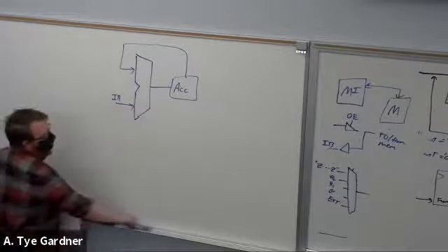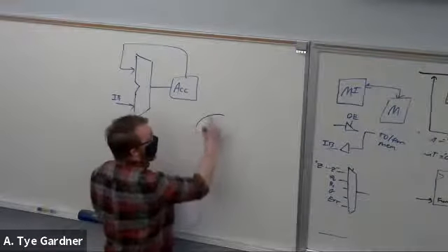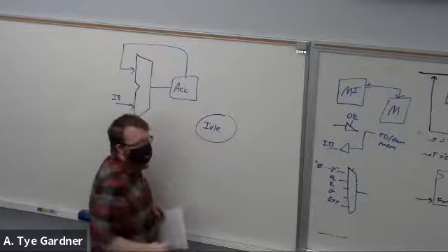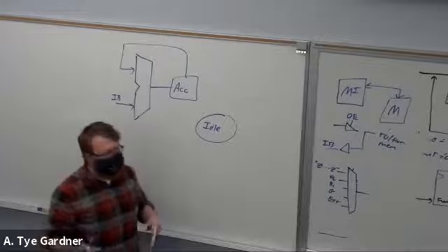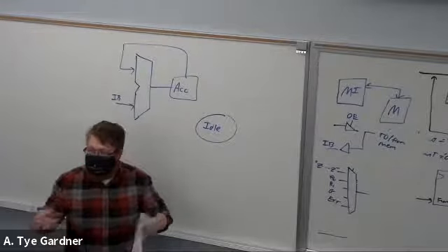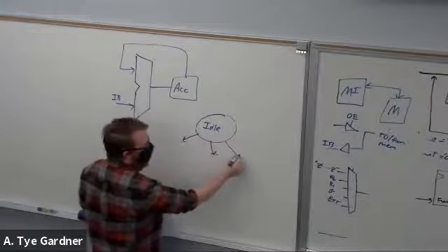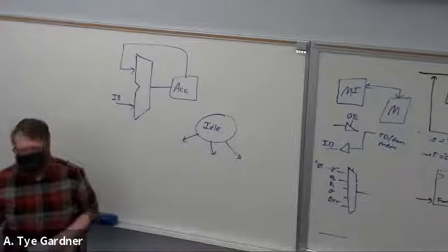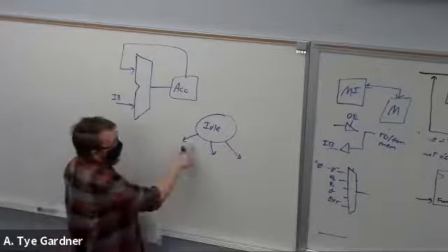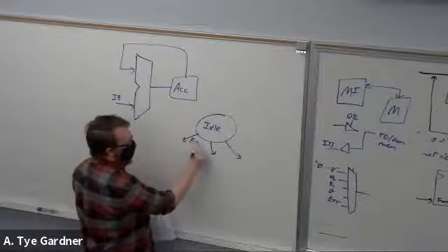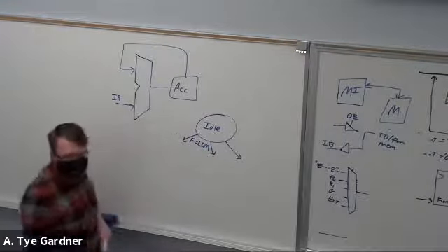So our state machine, when we start thinking about the control, we're going to start in idle, right? We're going to hang out waiting for things to happen. And each rising edge of clock, we're going to evaluate what state we go to next. But we could go to lots of states, right? Depending on what our function is. And we've been given a list of functions in project 2 to know what's coming. And so, if the function is equal to load from memory, LDM, right?